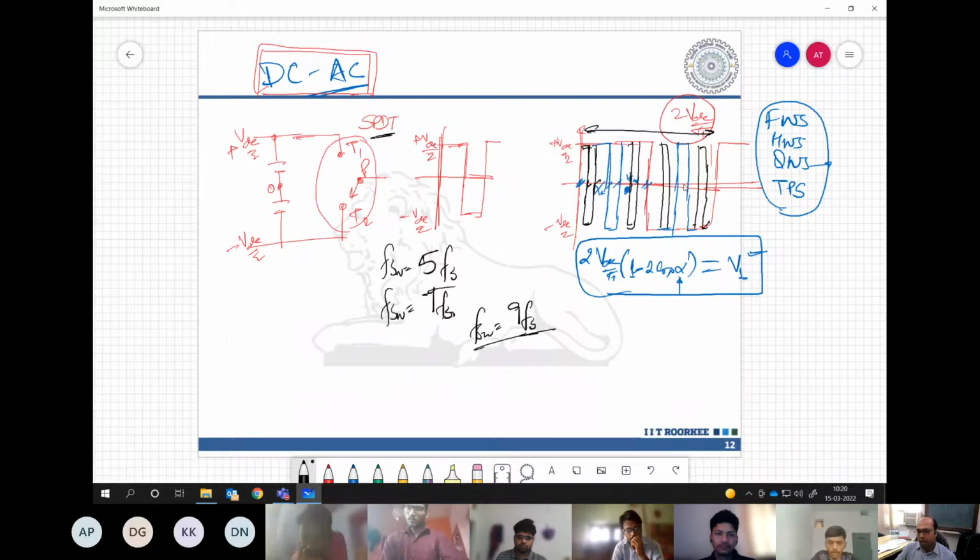It's kind of restricted here. It may be restricted because of several reasons: we have a high power system, we have a high speed system, and we are trying to reduce the switching energy losses, or we do not have the capability to operate at such high switching frequency. So in all those cases, we were doing that.